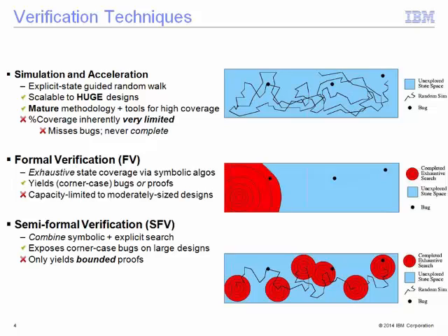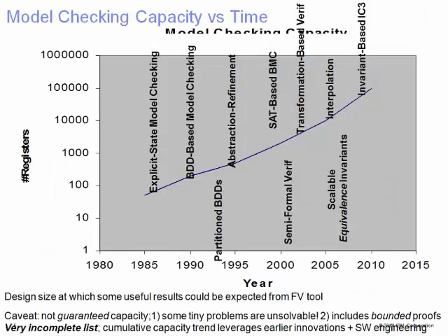Okay, this is again from the tool standpoint, over time, like in the late 1980s, right? So we started with explicit state model checking. There, the designs had 100 or 200 state variables. Now it has reached a point that it can handle larger scale designs, like several 100,000. So starting with explicit and BDD, and then SAT solving, and then bounded model checking, then later inventions with the transformation-based verification, which we will brief on, interpolation, and now property-directed reachability.